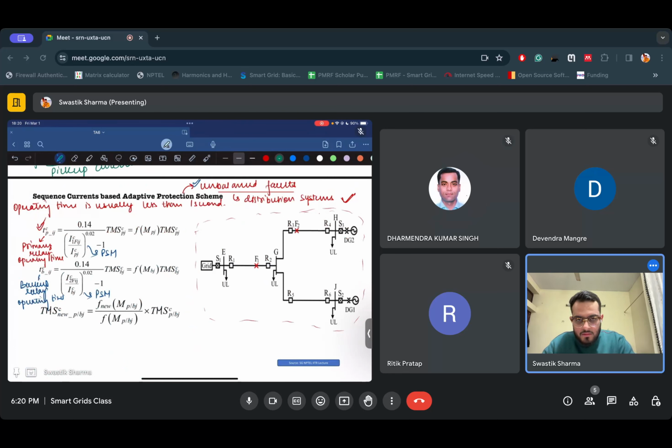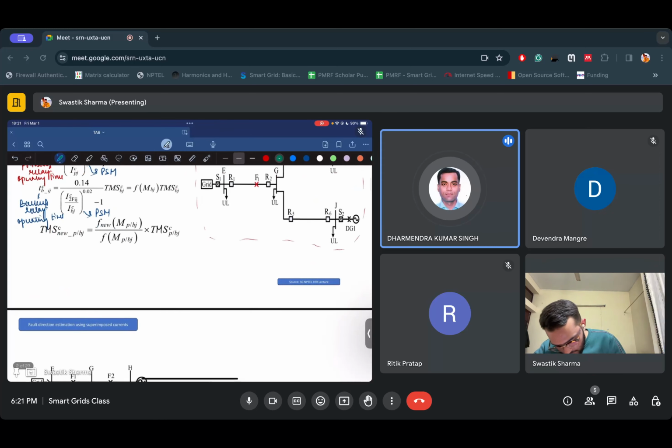Okay, so tell me one thing. Sequence components are generally derived for which quantities? Can we derive sequence components for balanced quantities? Will there be a negative sequence component or a zero sequence component for a balanced quantity? No, right? Sir, are you asking a question or telling? I am asking a question.